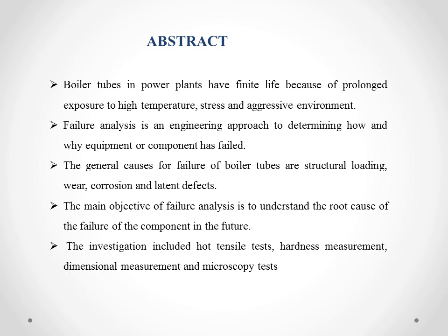Abstract. Boiler tubes in power plants have finite life because of prolonged exposure to high temperature, stress, and aggressive environment. Failure analysis is an engineering approach to determining how and why a component or equipment has failed. The general causes for failure of boiler tubes are structural loading, wear, corrosion, and latent defects. The main objective of failure analysis is to understand the root cause of the failure of the component in the future. The investigation included hard tensile test, hardness measurement, dimensional measurement, and microscope.